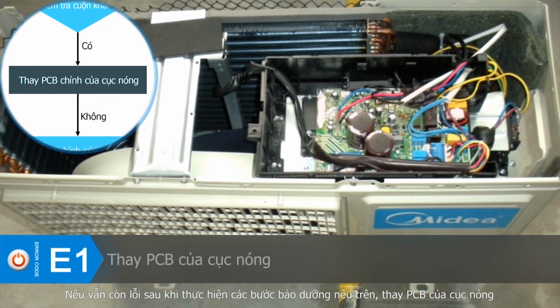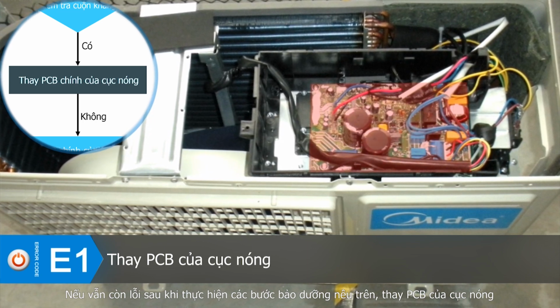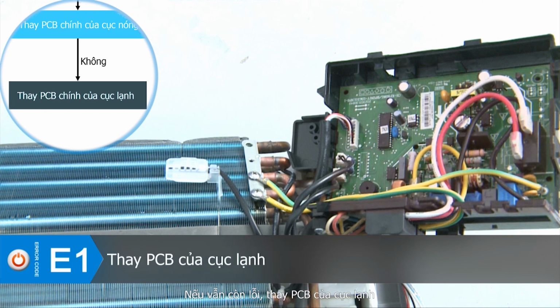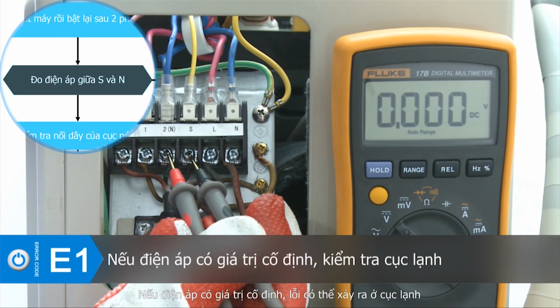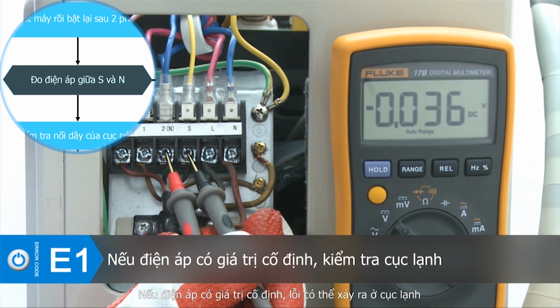If the error still exists after the maintenance procedure above, replace the outdoor PCB. If the error still exists, replace the indoor PCB. If the voltage is a fixed value, possible malfunction should have occurred on the indoor unit. Main attention should be paid for the indoor unit.